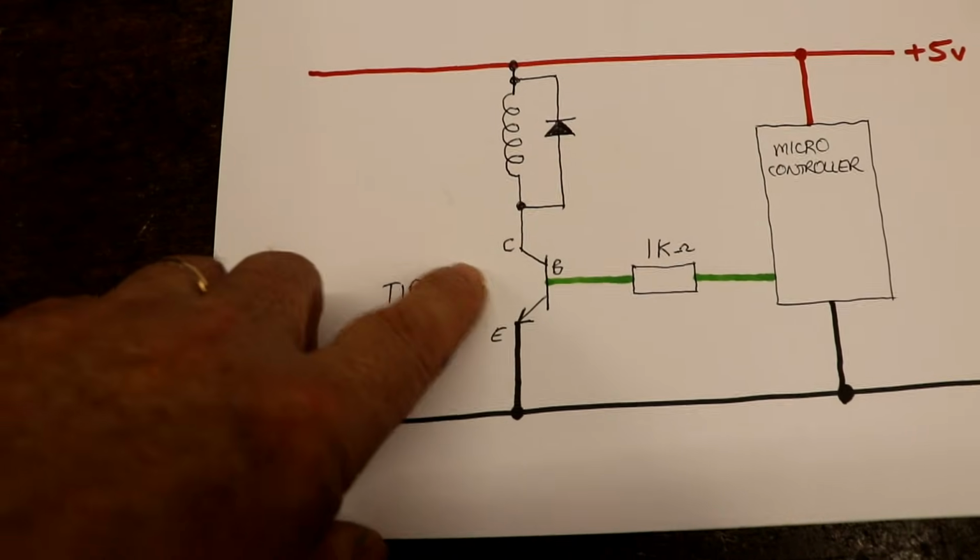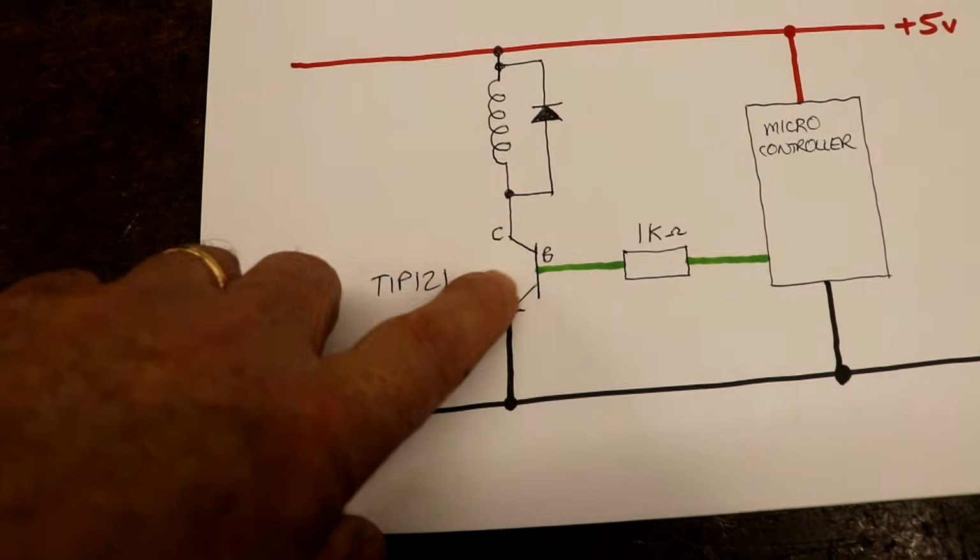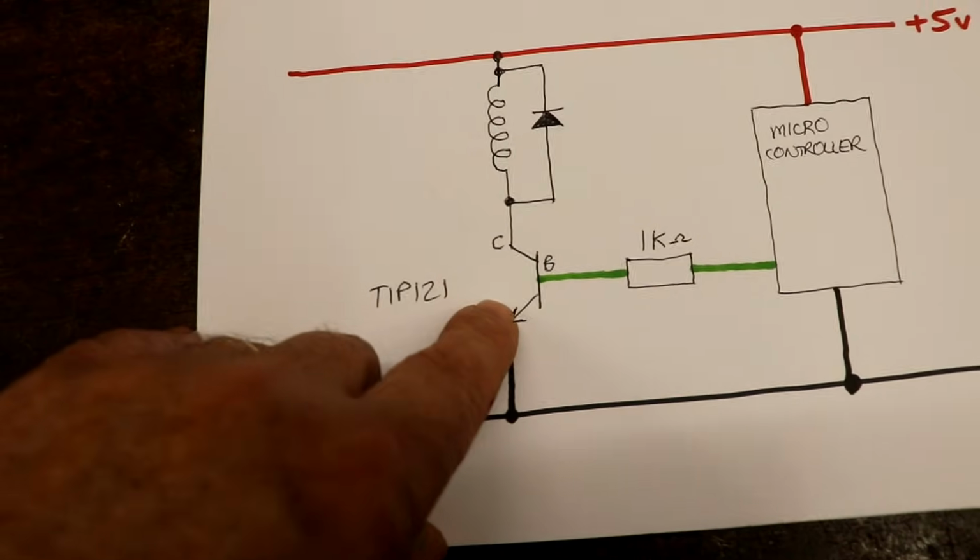For those of you who are highly observant, you may have realised that the H-bridge controller I was using was a dual one. It had 2 motor controllers, and that one was spare, so I could theoretically use that to control the solenoid. But I did try that several times and I couldn't get it working, and I think it's because transistors always have a 0.7 volt drop across them, just because of the way they work.